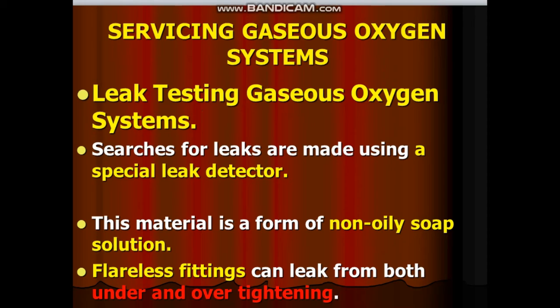Servicing gaseous oxygen systems. Leak testing gaseous oxygen systems. Searches for leaks are made using a special leak detector. This material is a form of non-oily soap solution. Flareless fittings can leak from both under and over tightening.